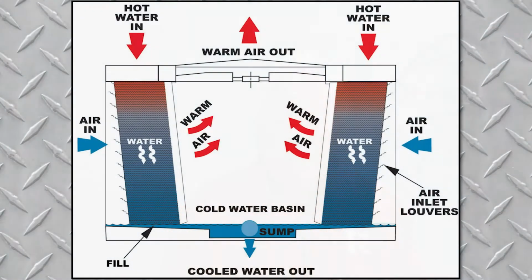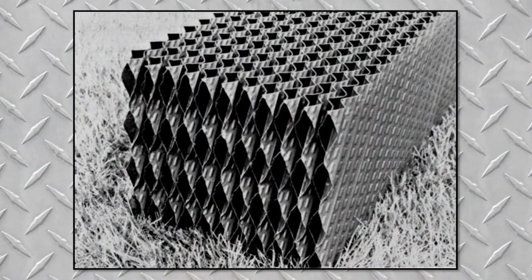Most cooling towers you're going to see will be wet because they can take advantage of evaporative cooling. The water in this case is not kept separate from the air, but rather it cascades down something called fill, which promotes evaporation. Here, the air cools the water while also evaporating a portion of it. The cooling tower fill, or packing, should resemble something like this. The goal of the fill is to spread the water out, maximizing its surface area to achieve optimal evaporation. Sometimes they will splash it around a little bit in order to increase mixing if faster evaporation is needed.